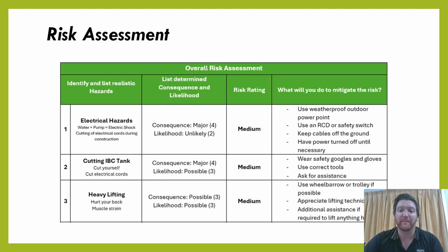Electrical hazards can be mitigated by using weatherproof outdoor power points, RCD or safety switches, and keeping cables off the ground. Cutting of the IBC tank can be mitigated by using safety goggles, gloves, using correct tools, and asking for assistance. Heavy lifting: use appropriate lifting techniques or ask for help if needed.